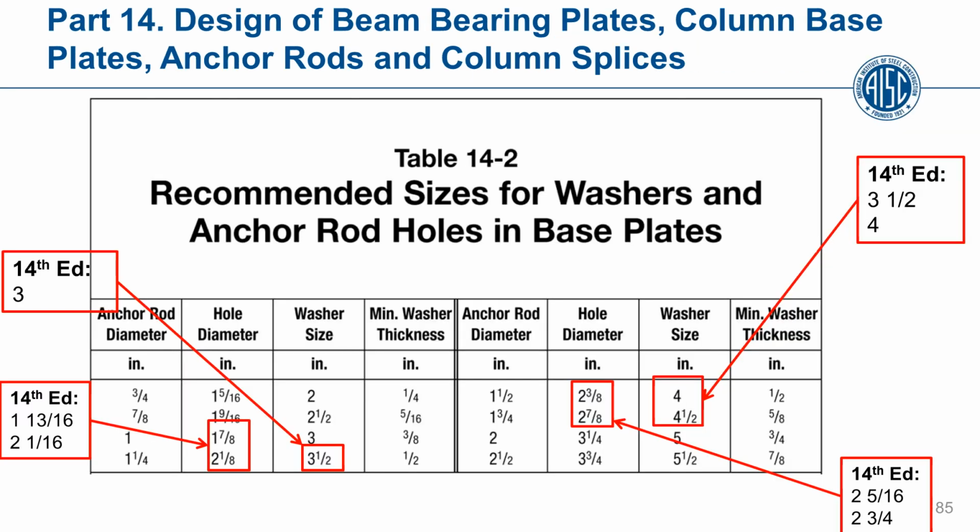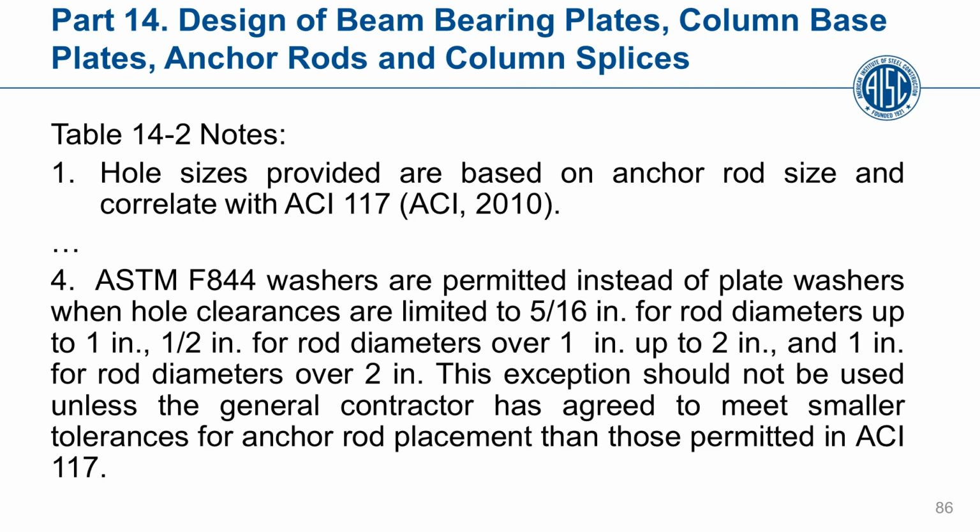Also, a change that occurred in Part 14 for the anchor rod hole sizes. In the 14th edition, we had sizes that were listed there, and you could see from this in Table 14-2, in the 15th edition, all of these sizes got larger. Now, these sizes got larger to accommodate what is required in the field for installation, and also it refers back to the hole sizes provided in compliance with ACI 117.